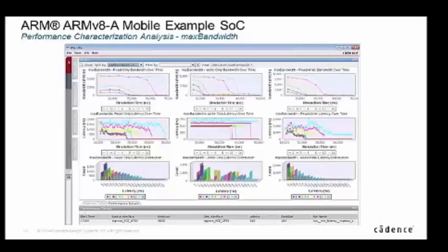If you remember this diagram where we've got multiple masters active, the key thing here is that we need to define QoS. We need to define the quality of service of our system and how it behaves. You can think of it as a dynamic arbitration, and it affects the interconnect components and the DDR.